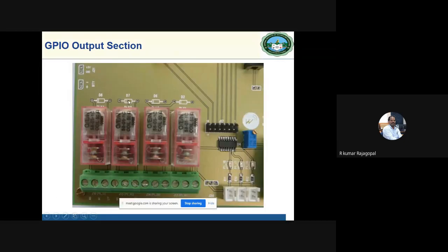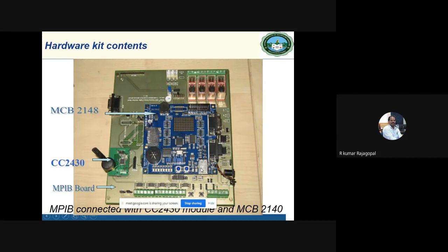Now the next level. These are the opposite machine. Assume the other machine has LED connections and relays. The output voltage from the terminal is usually 3.3 volt DC; some processors have 1.8 volt DC. The LED display option is available here, or otherwise, if you want to drive lights or 230 volt or 440 volt related drives, you can use the relays. So the input will be 0 to 3.3 volt, and the output may be on/off for AC or drive related signals. So in this case, this is the complete hardware.